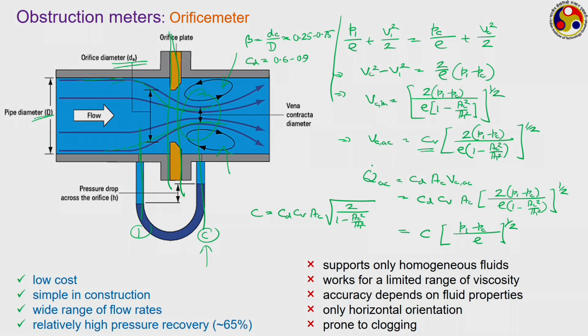Larger the flow velocity, larger the Reynolds number, the vena contracta may appear further downstream of the orifice location, and therefore it is not a fixed location for which you can mount your manometer to get the pressure reading. So, while P1 can be at any fixed location, for PC we have to be a bit experienced to locate its appearing location properly.